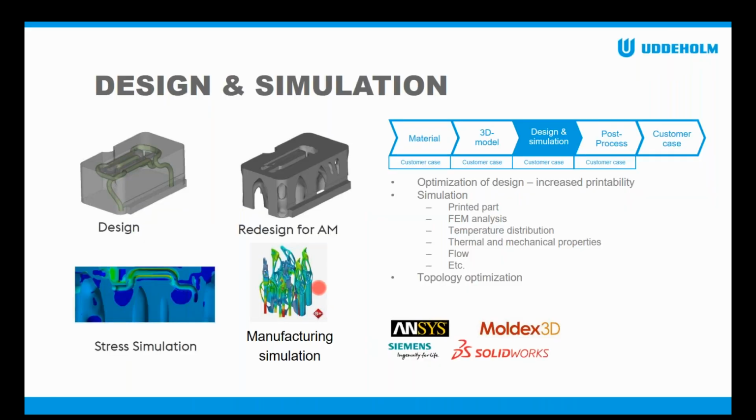Next step to improve a part would be to do some slight redesigns or simulate maybe the cooling in the part or something like that. So here we can also help to design and simulate your parts. And what I mean with that is, for plastic injection molding, like I said before, we redesign the cooling channels, and we do this based on simulations. Of course we can do it based on knowledge as well, but in order to get the best result, we always recommend to actually simulate the tool.